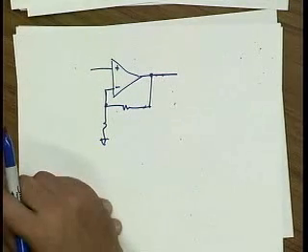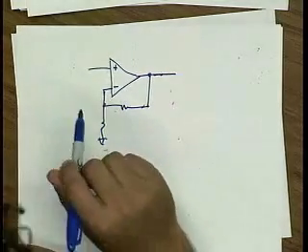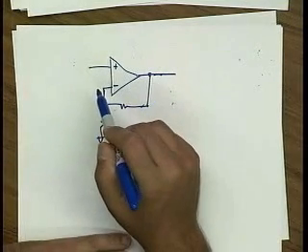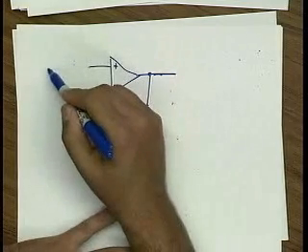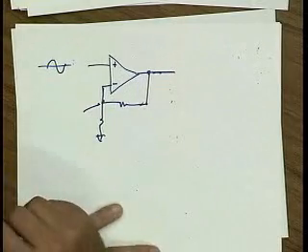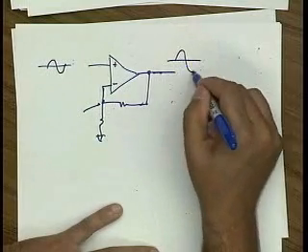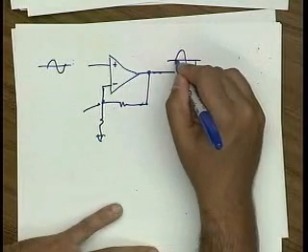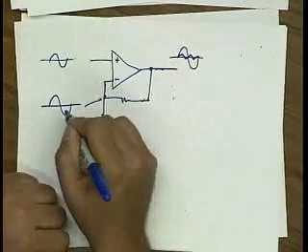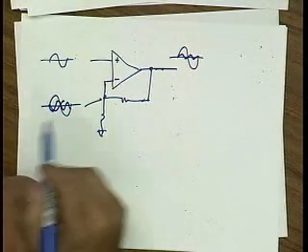What's interesting though is if you now look at the signal that's fed back, you'll find that the signal that's fed back to the input actually has a lot of distortion in it. Right? If I put a pure sine wave in here, and I look at this node here, you'll find that this node has lots of distortion in it. Whereas out here, it's again clean. But let's say that you find that the distortion level here is very small, but if I look over here, I actually might find that the distortion is quite large. Can someone explain what's going on?